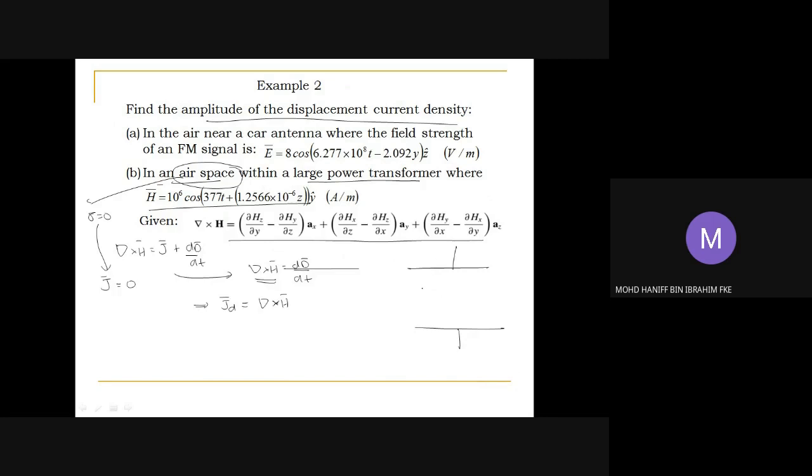The current can pass through this capacitor, although this is a perfect dielectric, sigma equals 0. So the current that propagates through this perfect dielectric is given by curl of H equals JD, JD equals dD over dt, which means that the current that passes through this particular perfect dielectric is actually a wave, and the wave is given by this time varying electric field.